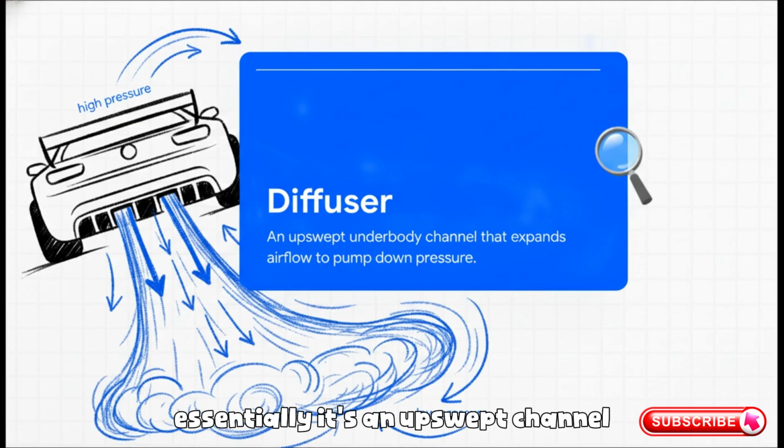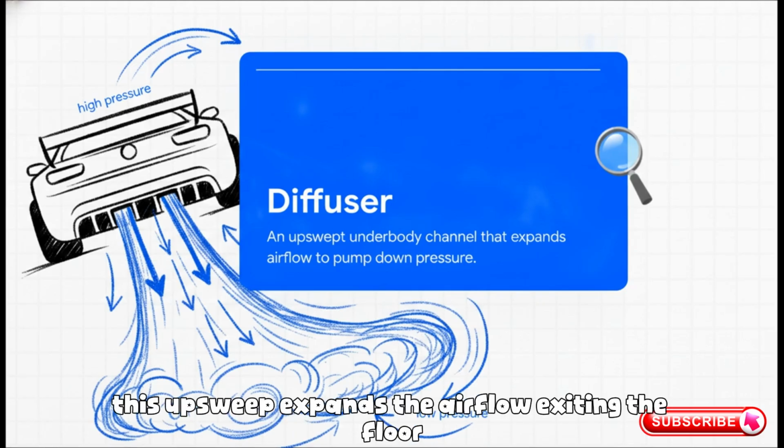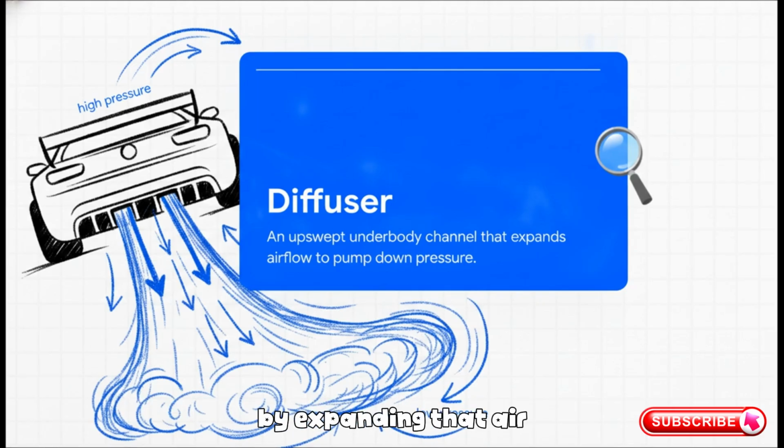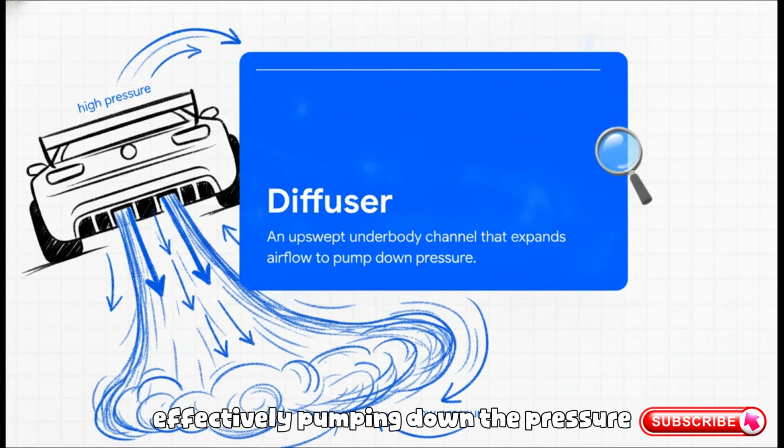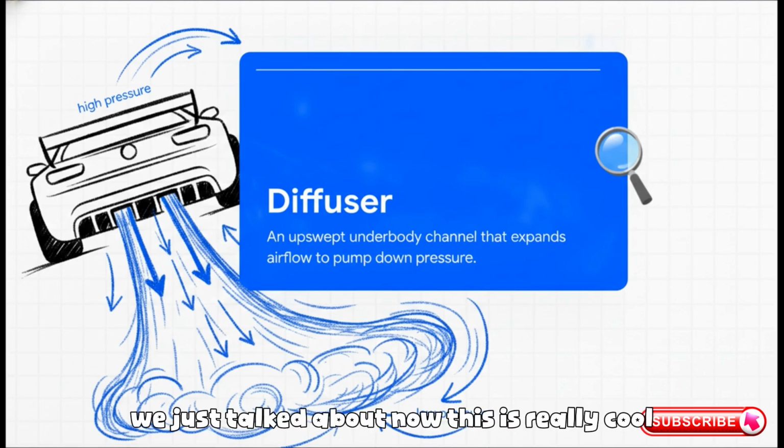Essentially, it's an upswept channel at the rear of the car's underbody. Because the pressure at the base of the car stays relatively constant, this upsweep expands the airflow exiting the floor. By expanding that air, it accelerates the flow underneath the car, effectively pumping down the pressure and creating that immense suction effect we just talked about.